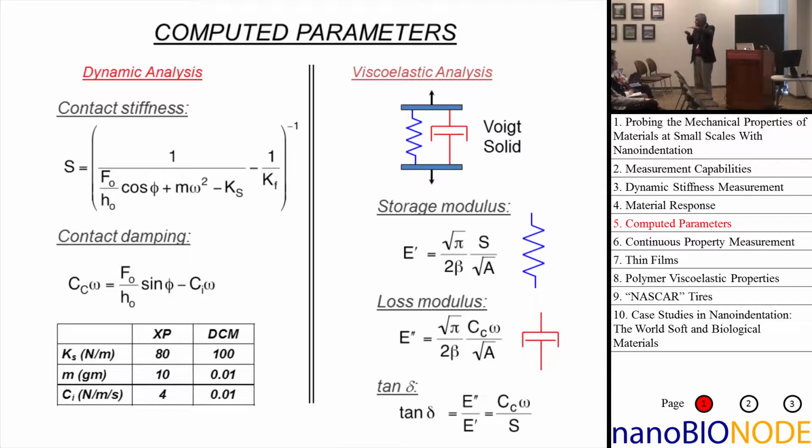As they move up and down a little bit, you have to move that air around, so there's a huge damping force created by the motion of that air in the parallel plate capacitor. Those things have a marked effect on what you measure as the contact stiffness. To get the contact stiffness out, you have to take the measured parameters from the Lock-in amplifier and subtract off all of the machine components that are also contributing. The same thing happens with the contact damping.